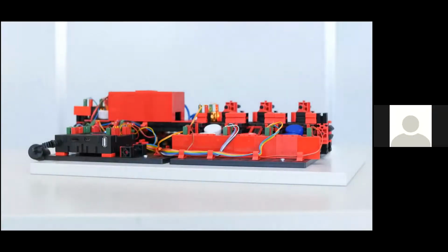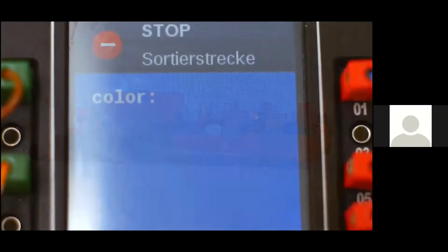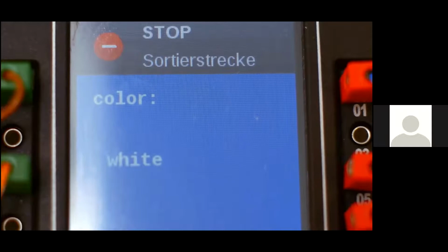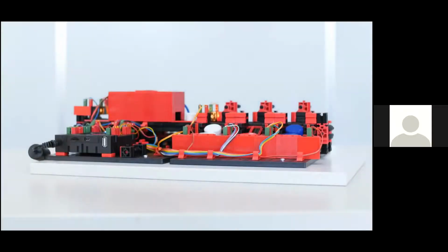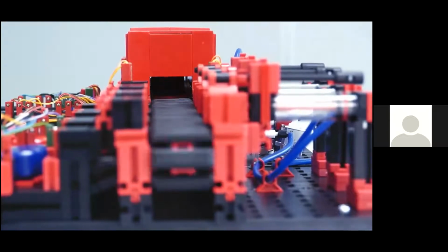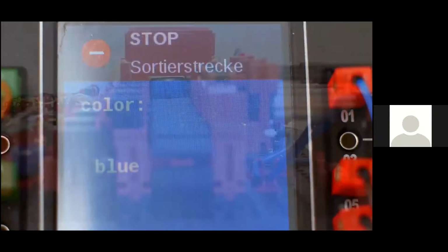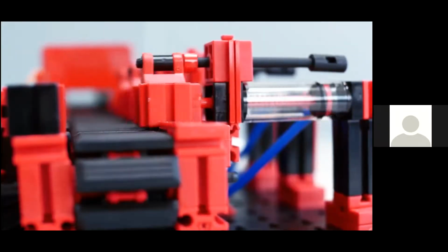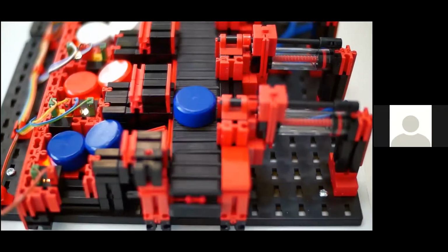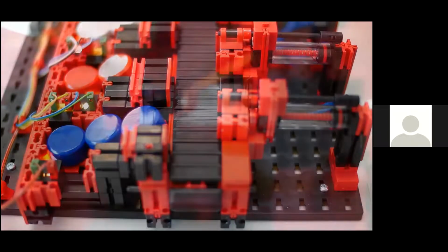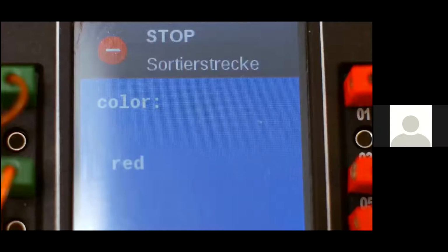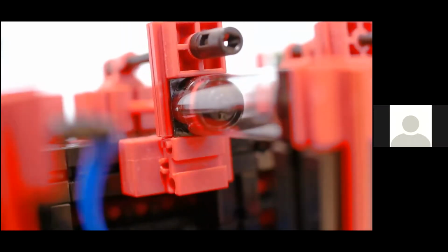Now, as with the models we've looked at before, the standard 24-volt version has a relay board for motor polarity reversal, and both the multi-pin connector, again 34 pins with a grid of 2.54 millimeters, as well as additional PCB terminals with push-in connections for all inputs and outputs. And again, you need to provide the PLC and the programming. The limited edition 9-volt version again comes pre-wired to a pre-programmed robotics TXT controller, and one 120-volt power adapter is required.